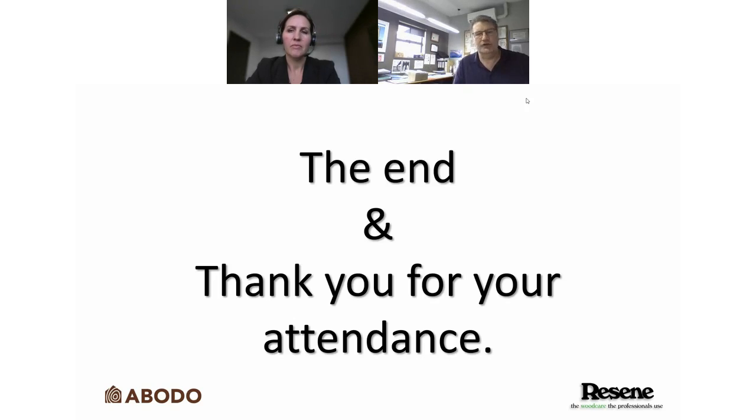So the best thing you could do from a durability point of view for stains is to put the decking down and then just leave it to weather for a while. You could pre-stain it and put it down and just leave it to weather for a while, and then the cells will break open a little bit. And then after 6 months or a year, you give it a clean and then put the stain on, to bring back its color. That's why we put the pigments in the stain. Then you'll start getting a bit more durability. But with decks, because they're horizontal, you are talking about an annual restain. Just saying.